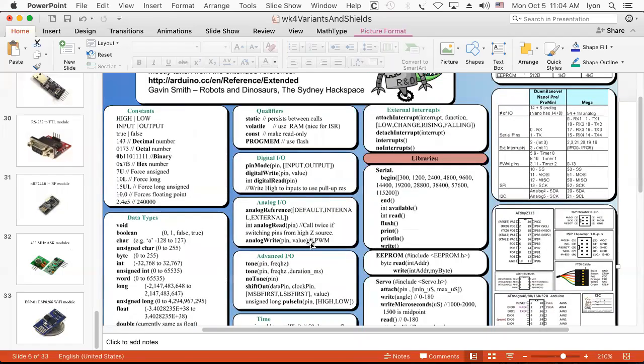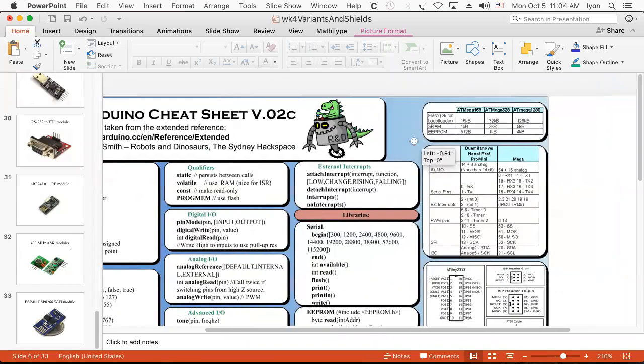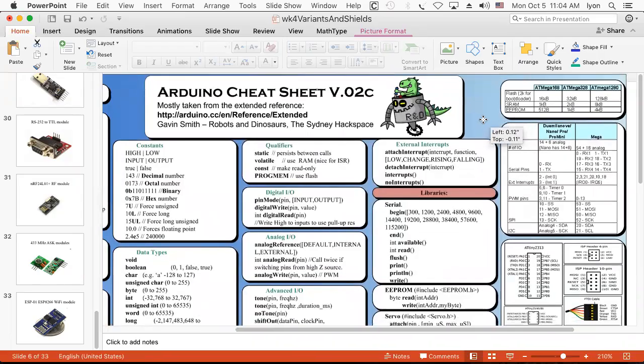So that's sort of an interesting little summary sheet. I kind of liked it because it had all this interesting Arduino stuff in it, as well as some general stuff that you might like to refer to. And then in the upper right, you can see your ATmega328. That's your Uno, and it tells you it has 1 K byte of EEPROM, 2 K bytes of static RAM, and 32 K bytes of flash. That's actually where the gist of the storage is on the ATmega, in your flash, 32 K bytes. So not a lot.